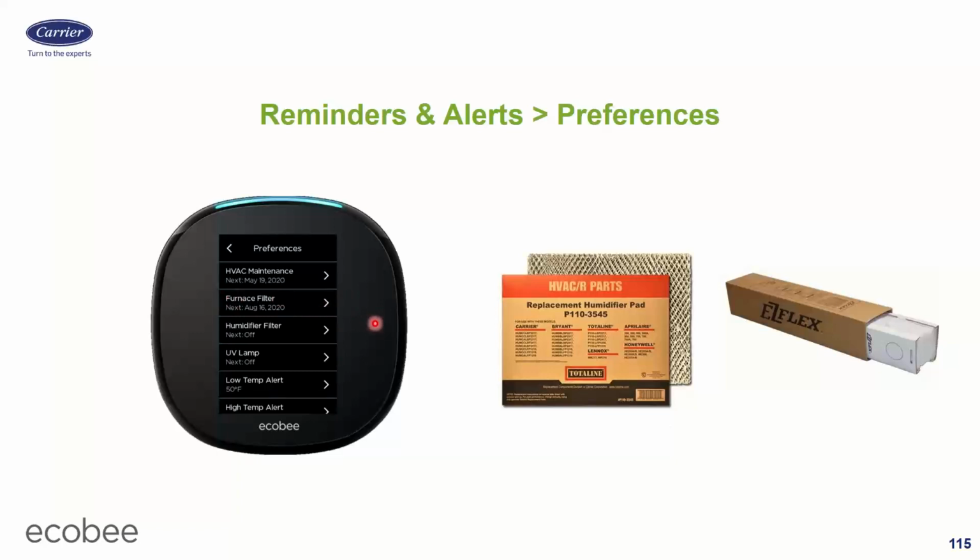Basically, you have to keep checking the filter to see when it actually looks dirty, or put a differential pressure sensor across there, your manometer, and measure when it's dirty, and then try to figure, well, it took 6.5 months to get dirty, so I'm going to set this thing to go off in 6 months. Kind of a pain. Humidifier filter. This is a humidifier pad. I don't know why they call it a humidifier filter. I've asked them several times to change it to humidifier pad. I think they just think that the word filter is more logical to the homeowner. So that's why they leave it there, because the homeowner doesn't know what a pad is. In any case, you can set this to go off whenever you want.